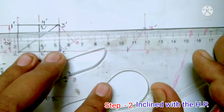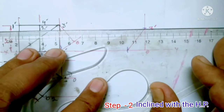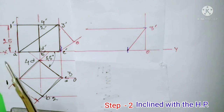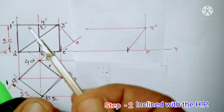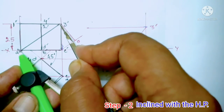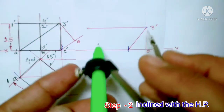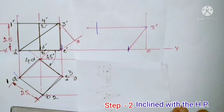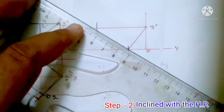Draw a line from 3' point parallel to the XY line. Now take this A'3' distance and cut it on the parallel line. Now join from point to point by a line.